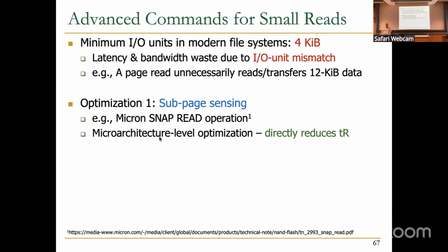That reduces the sensing time. You don't need to spend a long sensing time for reading 16 kilobytes. You can spend only enough time to read, for example, 4 kilobytes. I'm not going into the detail of that, but just to give you some idea that there are optimizations people can use to reduce the latency for sensing.